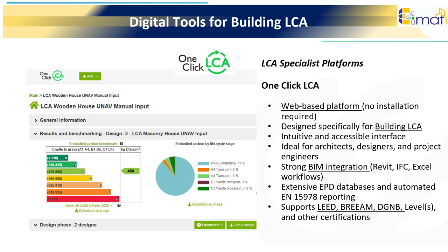Because it is designed specifically for building LCA, the workflow aligns naturally with architectural practice. It offers strong BIM integration, connecting directly with Revit, IFC-based models, and Excel quantity takeoffs, which significantly reduces manual data entry. Another major advantage is its access to extensive EPD databases, allowing users to assign environmental data quickly and consistently.